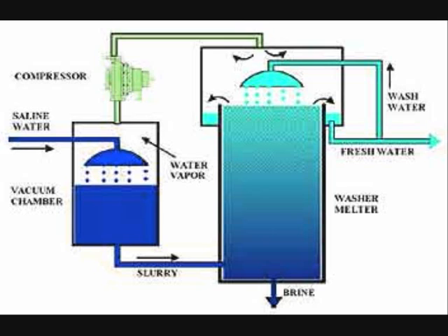You blow steam over a hole, and that sucks out the air from the hole. That creates a vacuum that lowers the boiling point of water, and as it boils it will lose heat, and as it loses heat it cools, and so you get cooling.